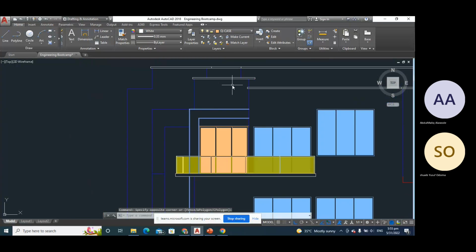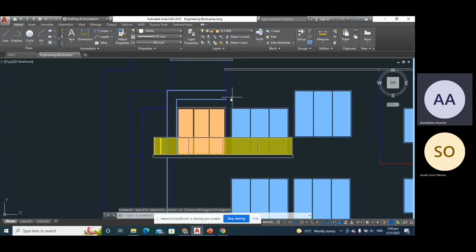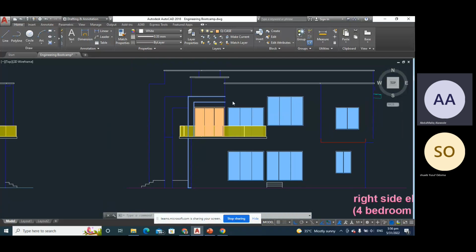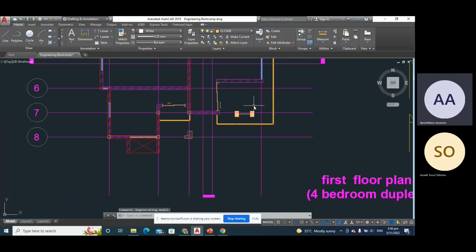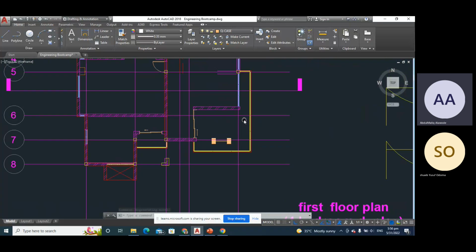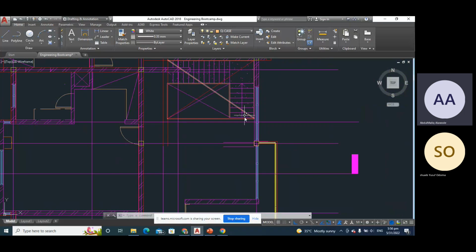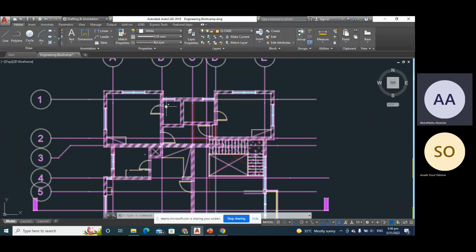It's a pergola. Sometimes the architect might say, I want this thing to be steel. If you want it to be steel, that means on the roof, we need to prepare a beam at this point, so they can weld or screw or whatever support they want to give to this thing. So they can install it here. You understand my point? When we get to the roof, we talk more about that feature. Thank God I saw that. Which other column did we take off? None. Okay. What's now left?